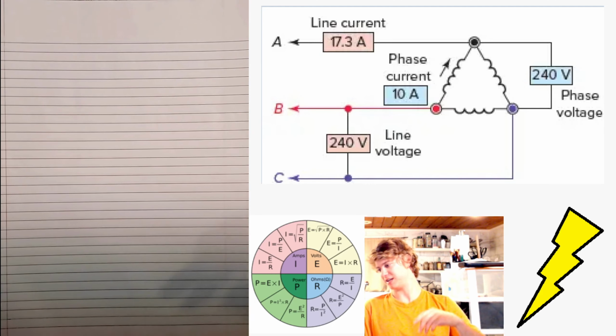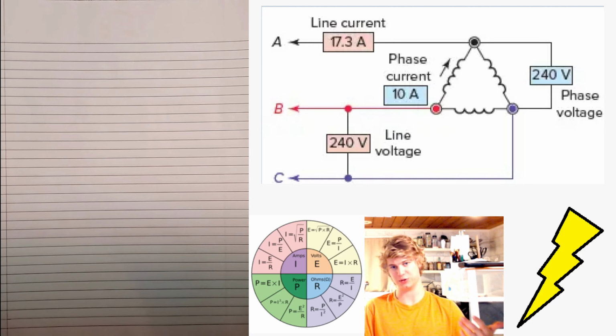Number 2, compare the use of a single-phase and 3-phase system with regards to 1, the amount of wire required for an equivalent size load. Okay, so think of one number for that. What's the percentage of wire that you're going to need with a single-phase versus 3-phase system, the same load? The variation in the amount of power delivered to the load, what's the efficiency? And 3, the actual physical size of the 3-phase and single-phase equivalent rated motors.